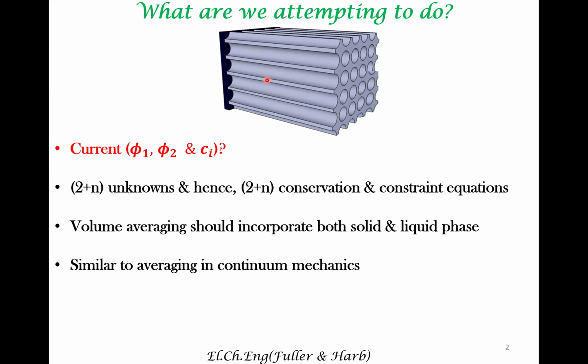When you try to define the density, you take a volume element which is much larger than the size of the atoms you are looking at. But this volume element length scale is less than the length scale wherein there is variation in these macroscopic quantities. For example, if you think about the density of a liquid, and let's say there is a temperature variation in the liquid, because of the variation in temperature, there would be density variation.